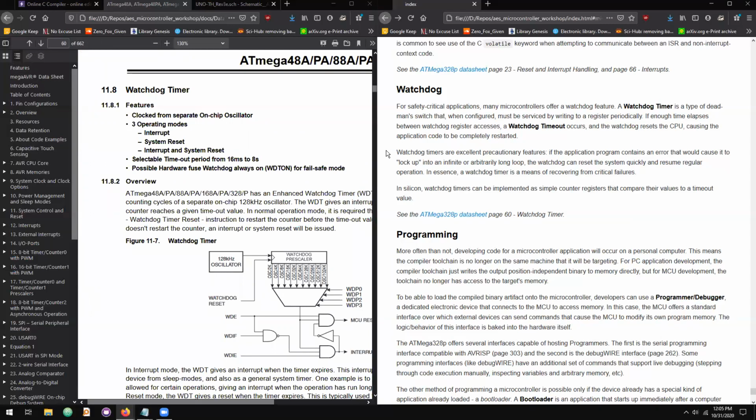Other applications where that's necessary, probably medical. If you have an implant driven by a microcontroller, you never want that implant to lock up because it's very difficult to access it when it's already in a body. So watchdogs are precautions, and the typical use cases are anything where the machine is difficult or annoying to access.